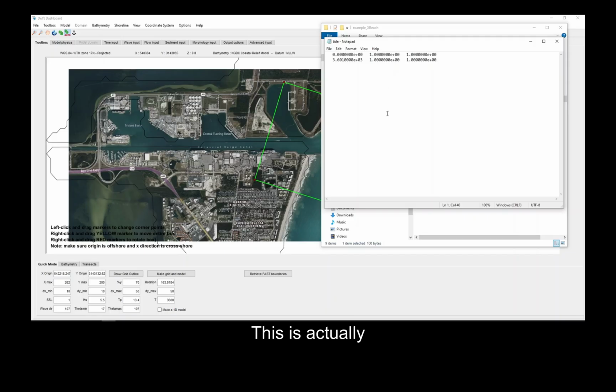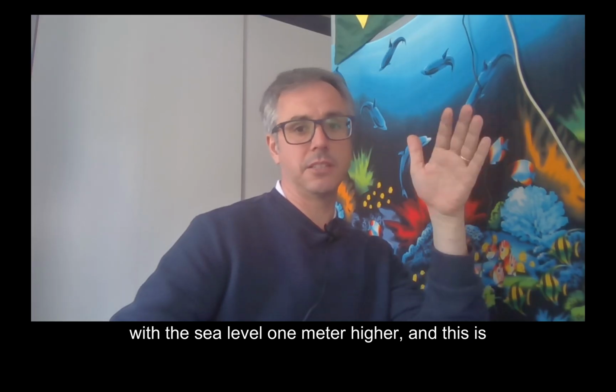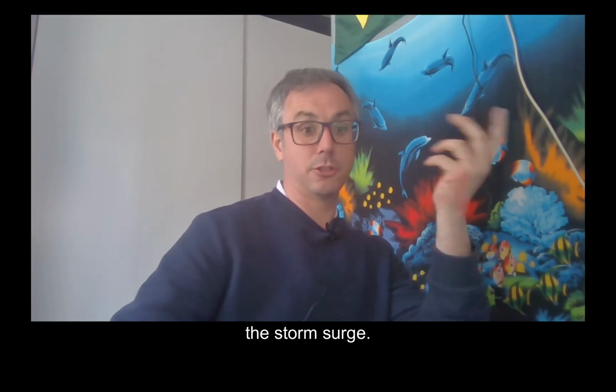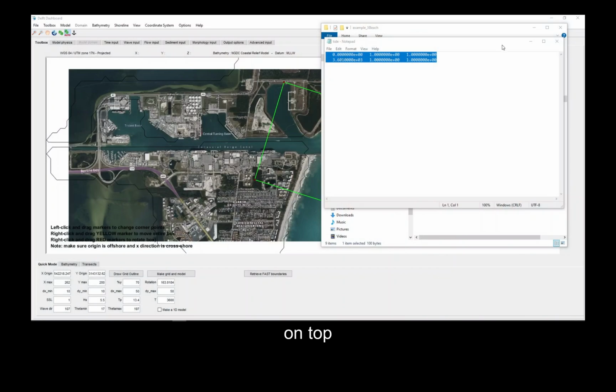This is actually the storm surge. So the storm surge of 1 meter that you put here. The storm surge, as also could be sea level rise parameters, is given inside here as a tidal level, basically. So we start with the sea level 1 meter higher, we finish with the sea level 1 meter higher, and this is the storm surge. So everything is going to run with 1 meter of surge on top of the normal sea level.